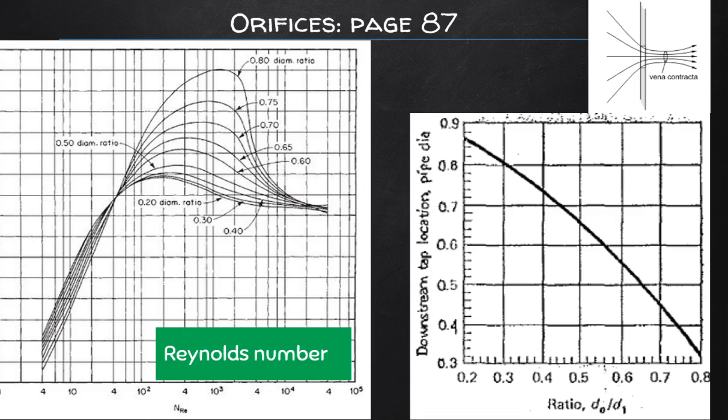However, for high flow rates, C takes on a more or less constant value for Reynolds numbers greater than or equal to 30,000, as you can see. And the graph then kind of stops, because you just more or less take a coefficient of discharge of 0.2 thereabouts.